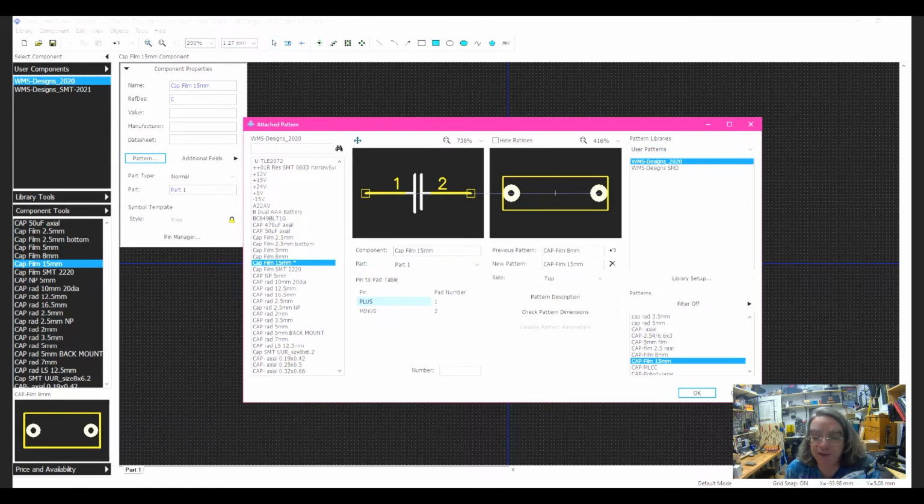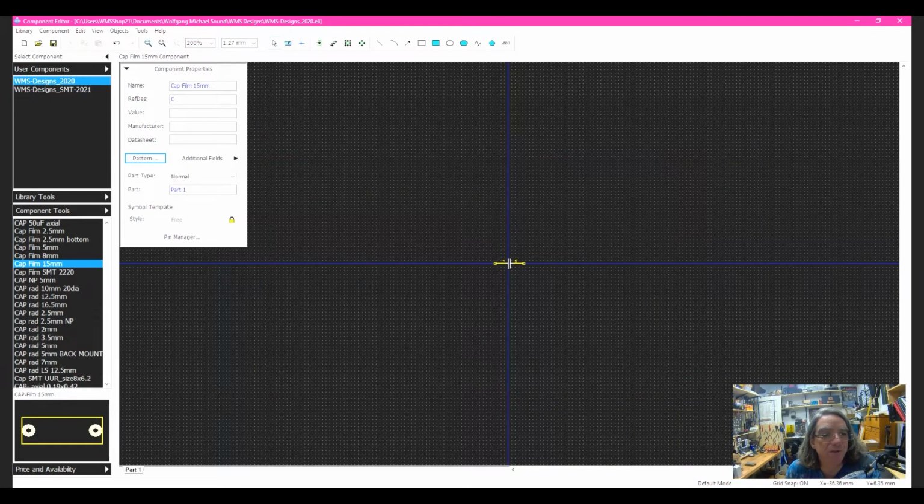And if you're creating these, one of the things you can do is pin one of the capacitor. And in this case, this is a non-polarized capacitor, so there's no real difference between pin 1 and pin 2. But this shows you which of the two is pin 1, which is pin 2. And that's really useful, particularly if you're doing transistors or things. You want to make sure the pins are where you think they are. So okay, and we'll save this library again.